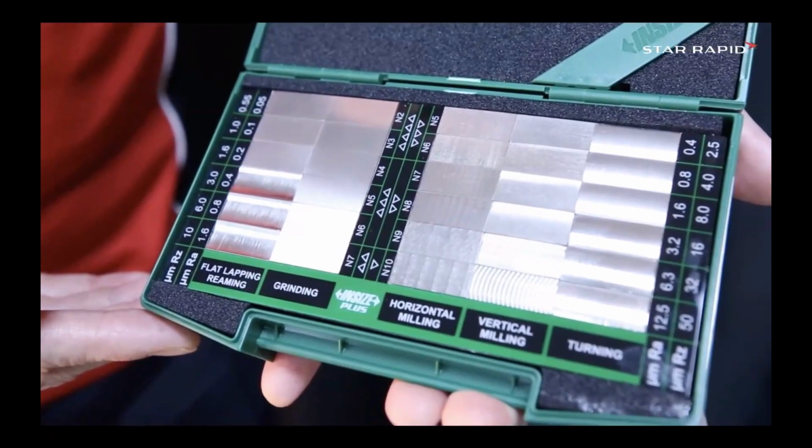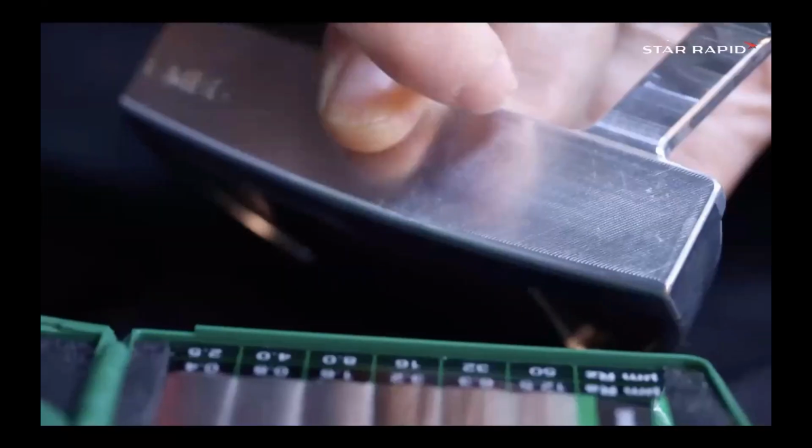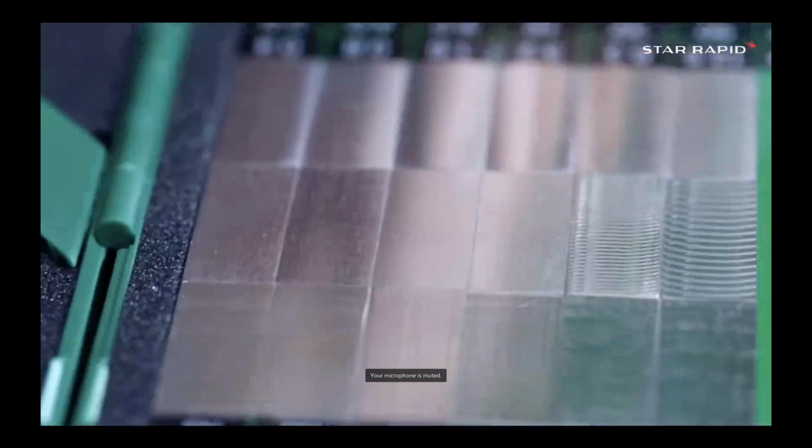I think that every manufacturing engineer who deals with CNC machining should have a set of these. You just look at your part and run your small pinky fingernail along the surface of the part, and then find that similar look and feel in the sample set. This is a really quick and relatively reliable way of knowing if your supplier is achieving the general roughness you require. Okay, that's all for this episode.